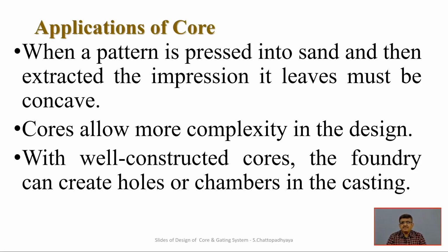In case of investment casting, there is no question of withdrawal because the pattern is melted away. But otherwise, where the patterns have to be used over and over again, the withdrawal strategy is complex, and has to be created with a very specific shape that is concave, and cores allow more complexity in the design.